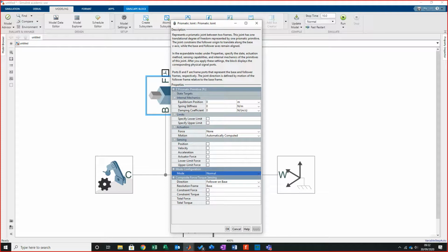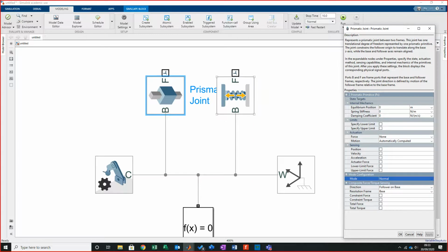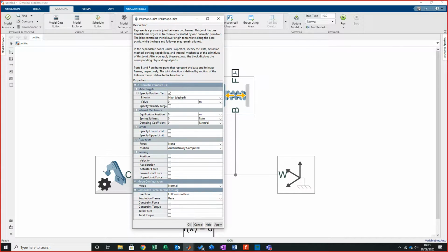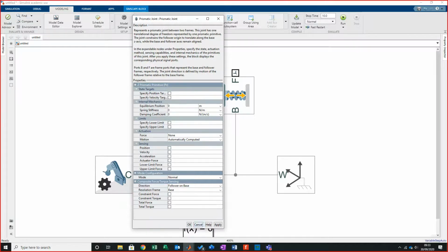Now the beauty of this is you'll notice that there's a spring and a damper coefficient in there. Not a lot of people know this, but the springs themselves, the material that's in them, actually have a natural damping and a natural spring stiffness to it. So you can drop in further refinement to the behaviour of that spring just on the material itself. That will then be combined with the spring force response. And then finally, your state targets. We can set a position, how something should sit, where it starts from, and velocities. We can even say how something is going to move at speeds, so we initially hit it with a key velocity. We're not going to use them today because I want to build in some elements to it.